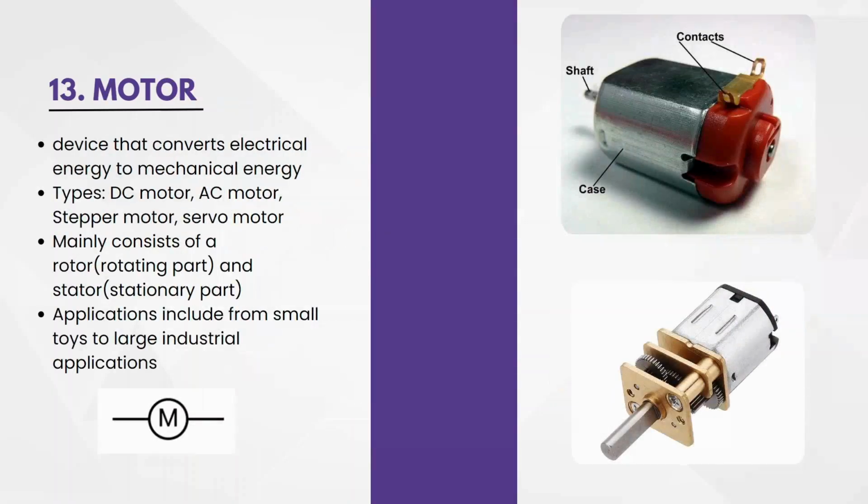Next, we have a motor. A motor is a device that converts electrical energy into mechanical energy. If you are confused between a motor and a relay, please understand that a relay converts electrical energy into a mechanical action, which is only the switching action. It will either make the contacts or break the contacts. That is the only mechanical action a relay will do.